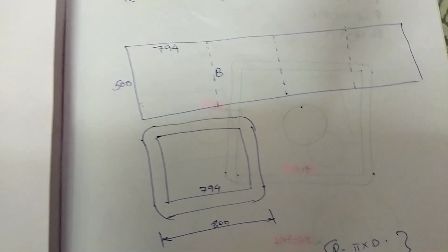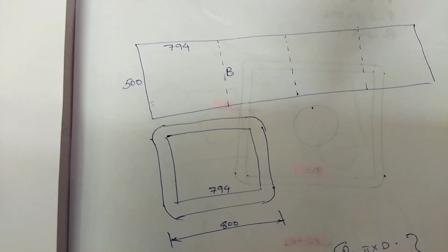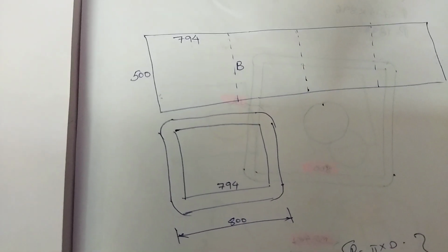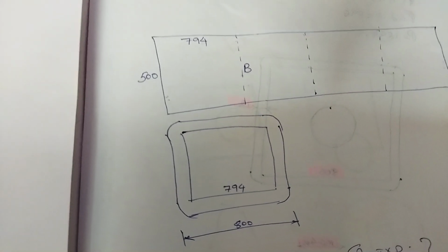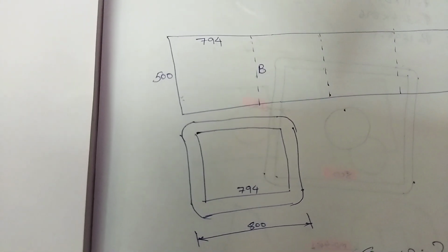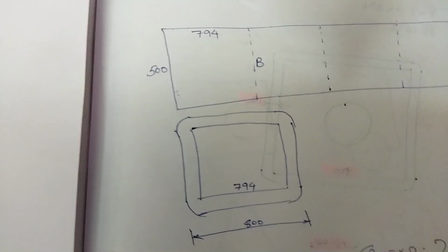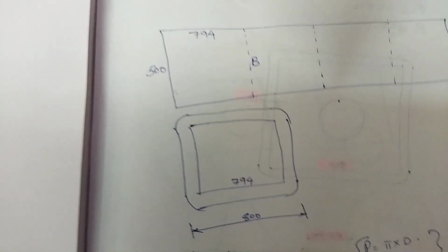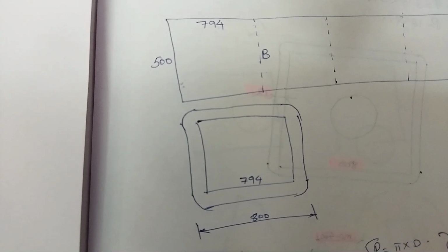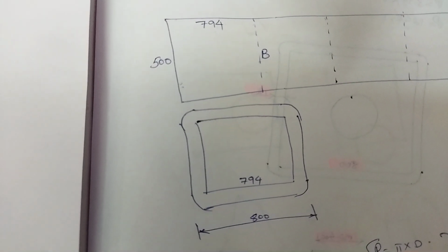Bending is done with a sharpened punch, and on its downside there will be a V block. In some other places, instead of sharpened we can use a curved portion also. Even so, all bendings will have one male and one female part.